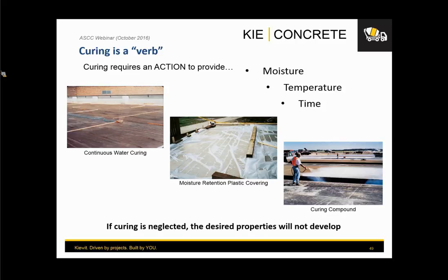You need to be careful then because, for example, people say you need to water cure certain mass concrete. Well, it depends what type of mass concrete. Traditional old mass concrete where you would do a lot of lean mixes that do not generate a lot of heat, sure, you can allow water curing in that case. That's the way that the Corps of Engineers and Bureau of Reclamation would do things 20, 30, 50 years ago. Today's structural mass concrete is different.